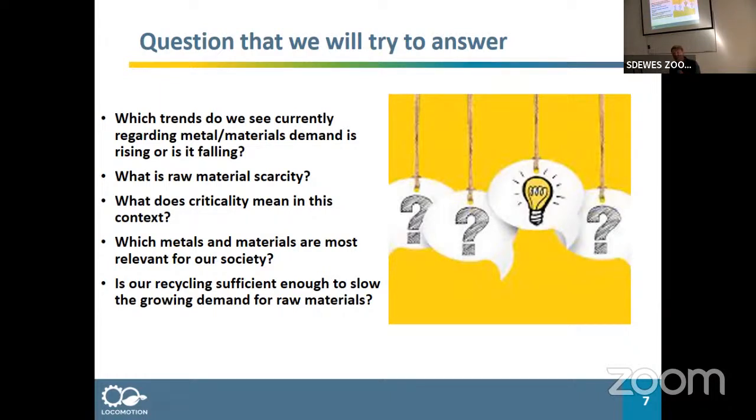That is due to limited material available to produce these products, and that results in high price spikes. That is actually the case, that we would have a worse technology in the future related to some of the examples today, because of the amount and the materials required to build the components of, for example, the batteries. Today you still need a lot of cobalt, nickel, etc. And then you switch to LFP batteries, which are, from the battery standpoint, worse, with lower energy density, but require less of these highly specific materials. Yeah, that would be the case of substitution and alternative technologies.